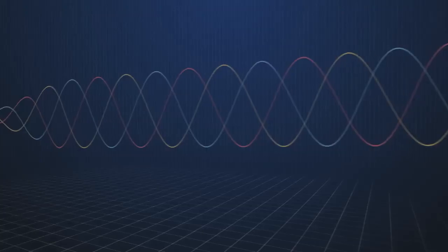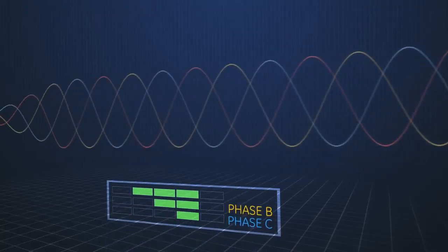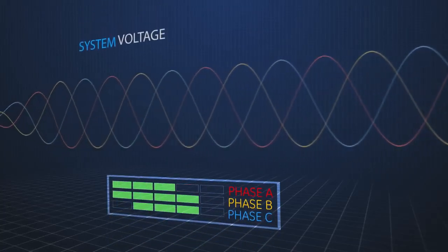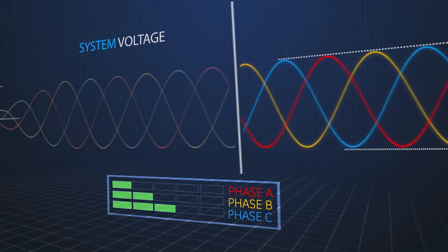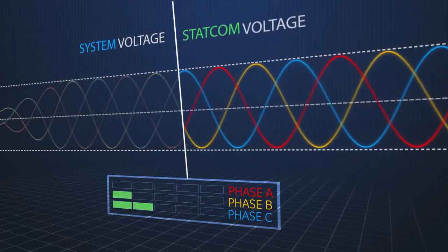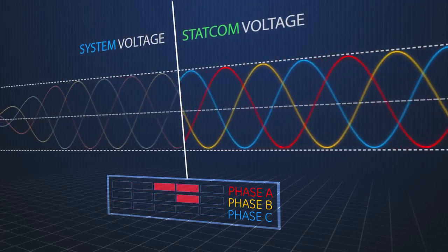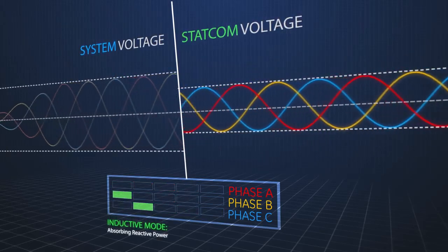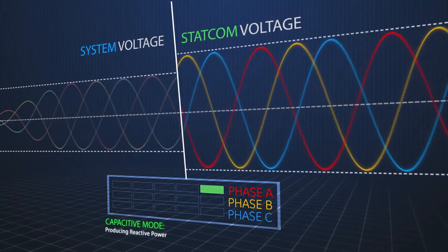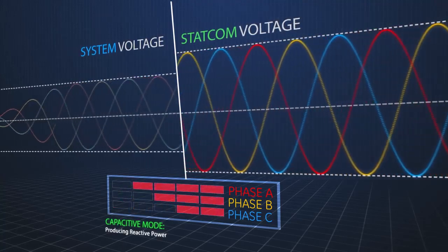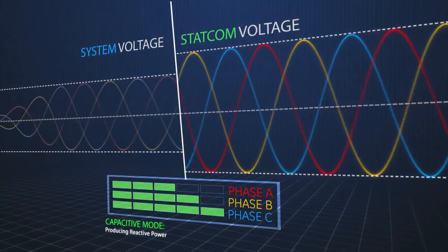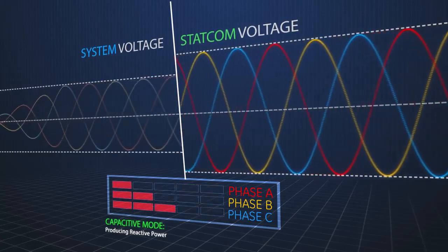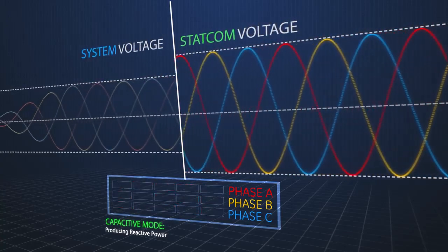The sophistication of the Statcom is that it is continually monitoring the always changing system voltage to maintain its output relative to the changing input. Simultaneously, the Statcom is rapidly providing either inductive compensation or capacitive compensation when required by the system. This complete process allows total control over system compensation and helps to maintain grid stability and boost efficiency.